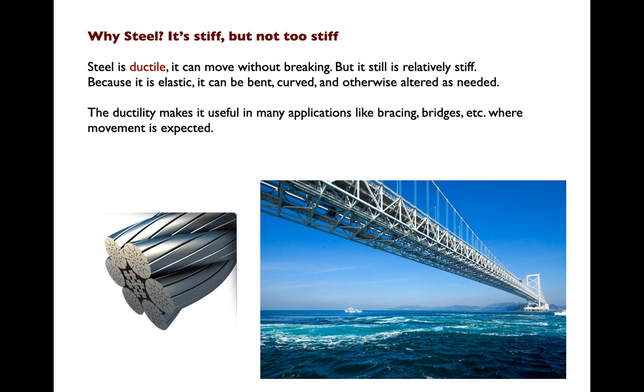Steel's ductility also means that if we're anticipating a lot of movement or a lot of deformation, this is one material that can handle it. Concrete is going to crack or break if we deform it very much. Steel is going to give. It has a very, very wide elastic range. And therefore, for a project like a bridge, it's going to be very handy because it's going to absorb that movement or that deformation without any permanent damage to the structure.